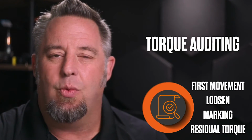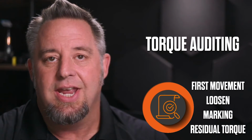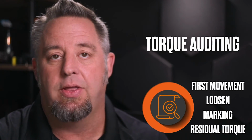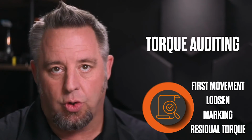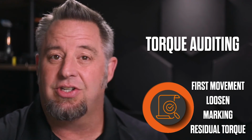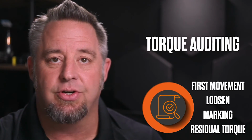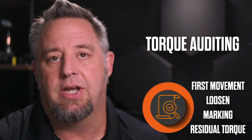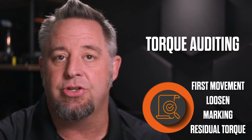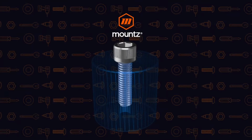And so one other fact on residual torque that is somewhat notable is that once we remove the tool from the application, there is no more torque in the fastener. So this is basically the tension that is left. Now there is a slight bit of torque that may be present because of the torsion that is in the fastener itself, but for us to be able to measure the torque, we actually need to get that fastener moving again to be able to measure what that torque is. So that's just a little note on residual torque.